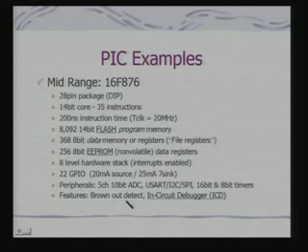What is brownout detect? When there is a voltage level fluctuation, one case is power out, and when there is power out I go to the reset state. Brownout detect is that when there are voltage level fluctuations, I can detect that and go to a predetermined state.